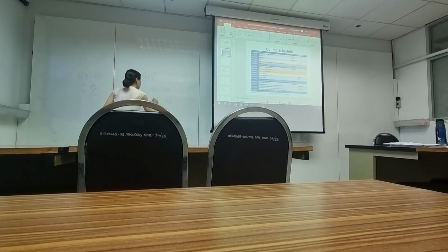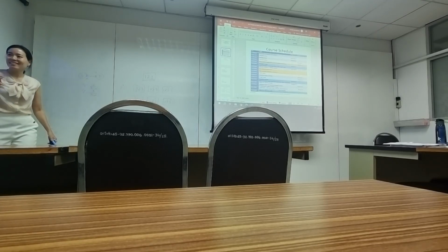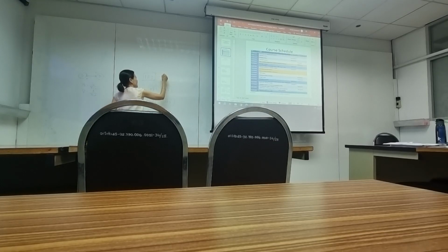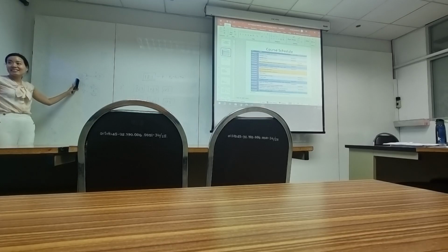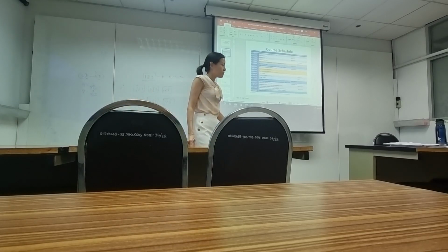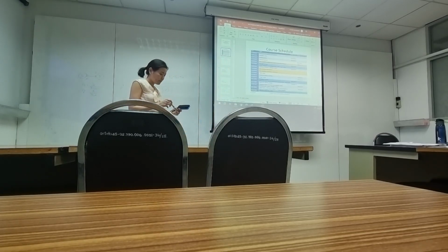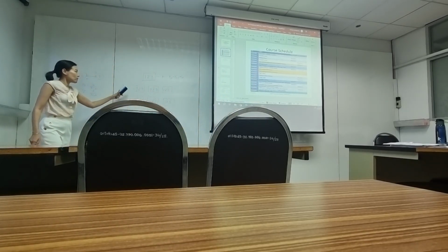And the easy thing about this is that if your devices only have two states, the probability of the state will be just equal to the probability of one being up times the probability of two being up and three being up, right? This would apply only when this is the case, okay? And we have done that in our lecture. So that is the analytical method that we have tried.